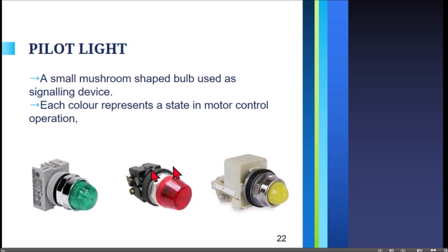Green indicates run, or the motor is running. Red is stop or idle. Yellow, sometimes orange, indicates a fault or emergency, meaning there is a problem on the motor.